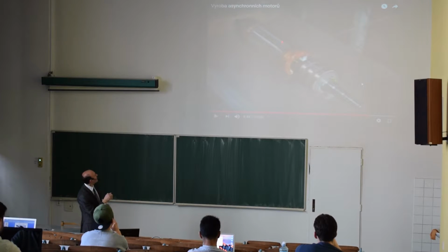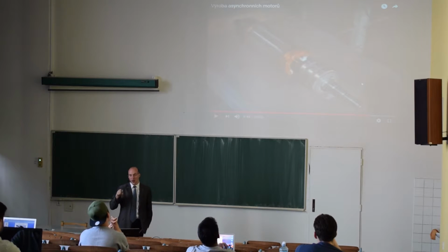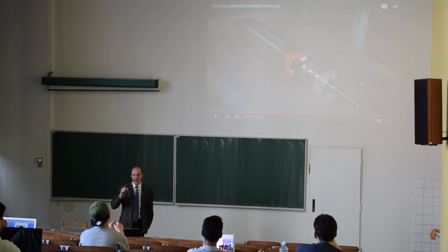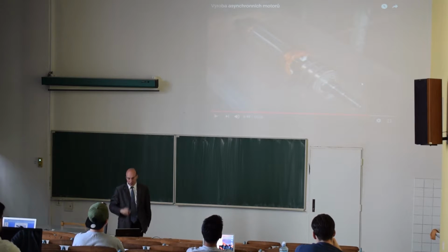Okay, so this is the rotor, the winding, and it's a three-phase winding that is connected to those rings. And those rings are connected then through brushes to a terminal box that is outside. So compared to a DC motor, this is only a ring. It's not a commutator, so it doesn't have individual sections. It's easier to produce. You just have 3 rings and 3 brushes, and that's it.